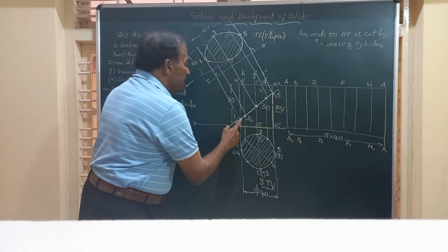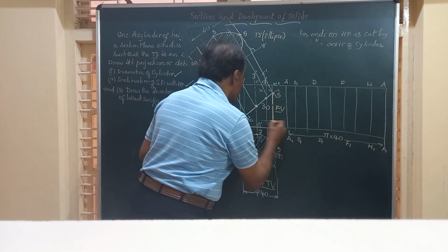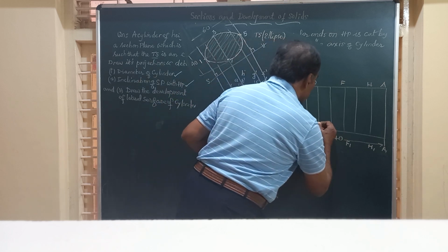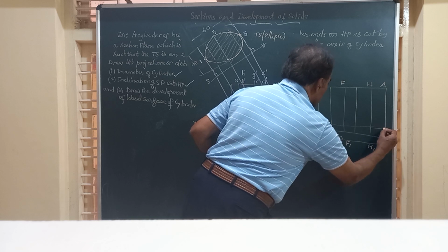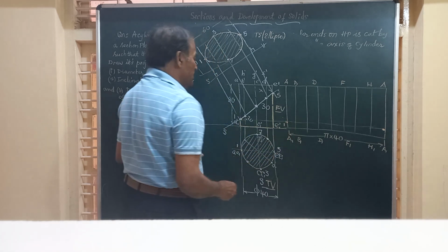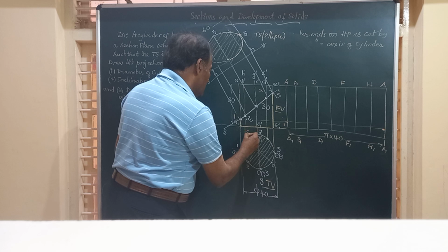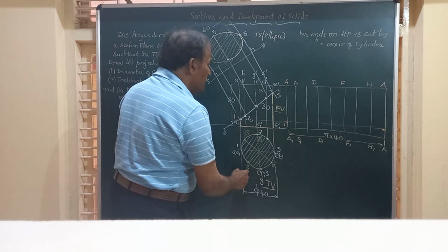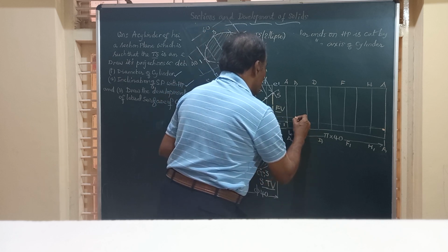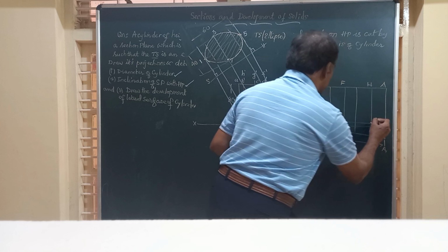Friends, the point 1 is on generator AA. So simply draw a horizontal line from there till it touches AA. Extend that line till the last. So this is going to be your point 1. I will mark here. And then 2, 2 and 8, 8. 2, 2 is on BB, 2, 2 at this height, and BB, and similarly on the other end you are going to get a point on HH.